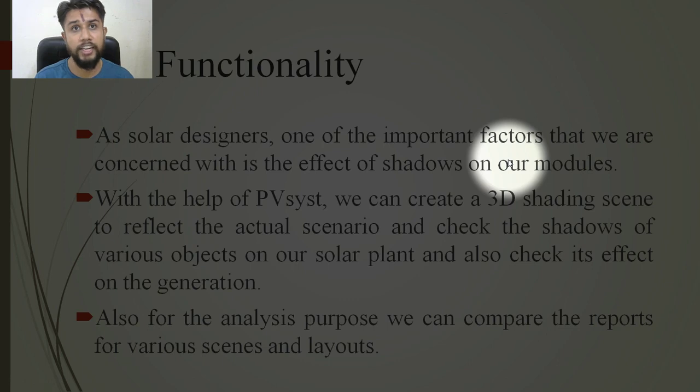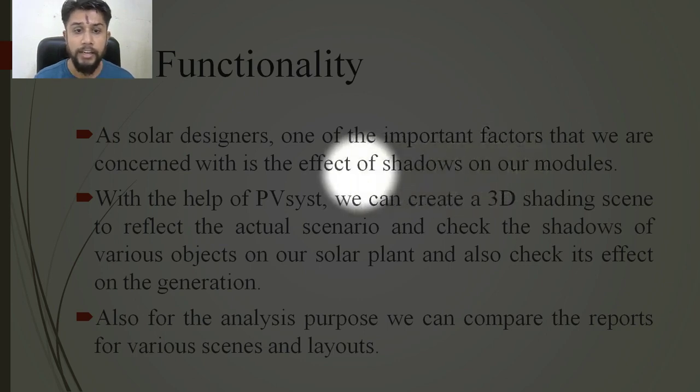How much shadow, and at what time the shadow is falling on the power plant or some amount of panels, has to be taken care of while designing a solar PV power plant for a specific location for the consumer. With the help of PVsyst, we can create a 3D simulation to reflect the actual scenario and check the shadows of various objects on our solar power plant and their effect on generation.